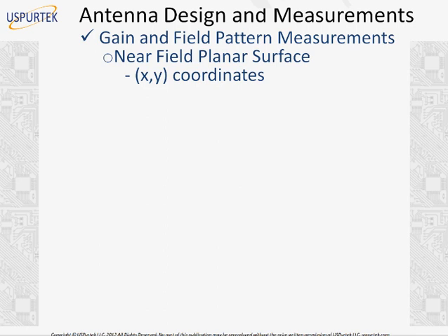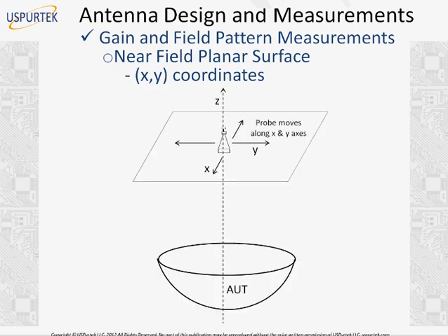But still there is an alternate technique available which has been devised to overcome the limitations of the open area test range or anechoic chamber, because they are expensive sets of equipment too. So if you have the software available that computes from near field to far field, you could use that technique too. But in general, we will not use a near field measurement. It's not recommended to do measurement in the near field unless you have the conversion software available, which will convert these measurements into the far field pattern.